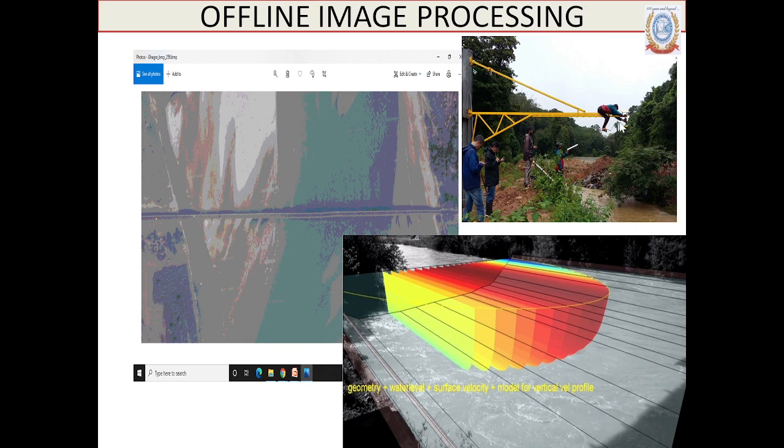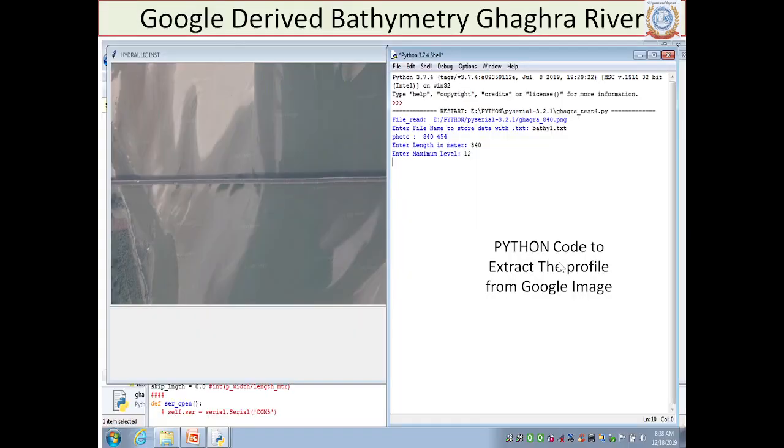All these are point measurements here. This is the calibration point. This is in Karnataka at Sakleshpur. You have the camera at the side. This is the camera. Here you have level sensors. This river stream gets a very high downpour and the water will flow up to this level. During installation we installed in a very lean period, and the heavy flood passes in a few hours, so it won't get noticed unless you use the camera technique to monitor it.